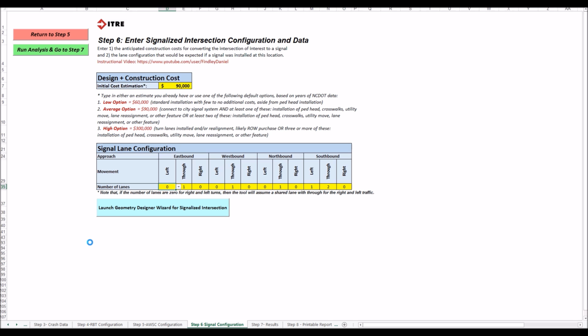If a level of service F is projected, the user can return to the previous steps and make adjustments to the period of analysis, geometric configurations, or other inputs to address the LOS of F as appropriate. For some intersections, high levels of demand may lead to an LOS of F regardless of the geometric configurations of the facilities. In such cases, users can use the comments section of the tool's printable report to explain related recommendations.